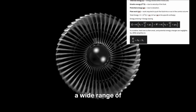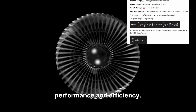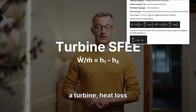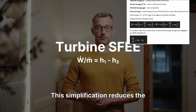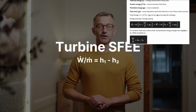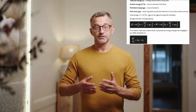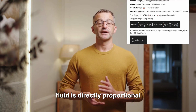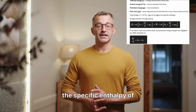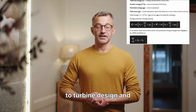The true beauty of the SFE lies in its versatile application to a wide range of real-world engineering systems, such as a steam turbine, where it helps analyze performance and efficiency. In the case of a turbine, heat loss to the surroundings and changes in potential energy are often considered negligible. This simplification reduces the SFE to W dot over m dot equals h1 minus h2, making calculations more straightforward. This simplified equation clearly indicates that the work done by the turbine per unit mass of fluid is directly proportional to the drop in the specific enthalpy of the steam as it passes through the turbine. This principle is fundamental to turbine design and operation.